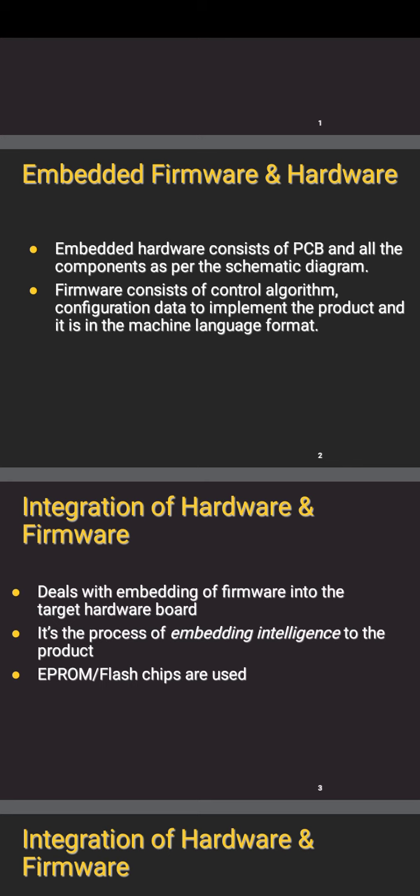If the product is having no operating system and if it is having code memory, then the firmware is integrated in the code memory. If it is having no operating system and no code memory, the firmware is either in the on-chip processor memory or off-chip memory like flash memory or non-volatile RAM.